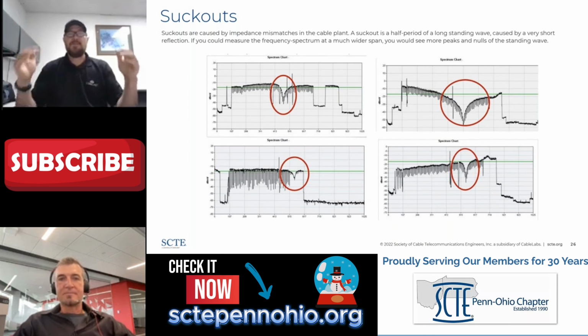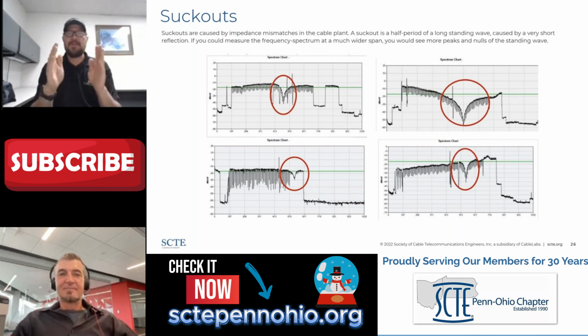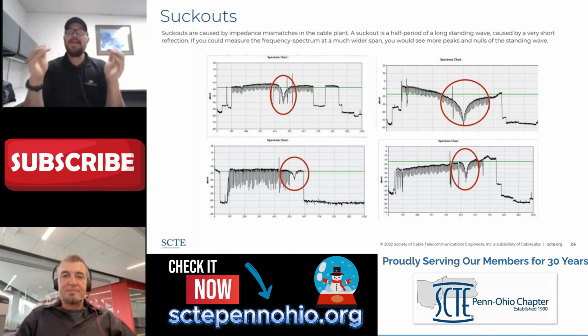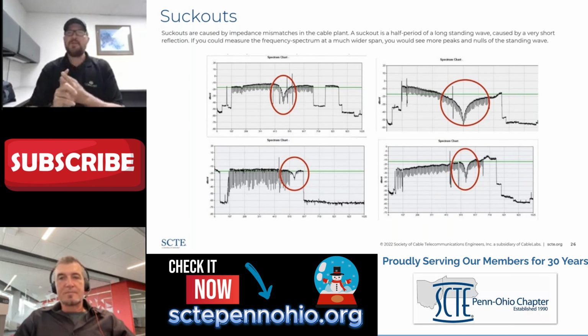Oftentimes when you see a suckout, you may also have a leak at 600-700 megahertz because of the geometry, the size of the component, and the fact that it's defective, meaning water corrosion or something impaired. So it's not uncommon to see high frequency leaks and suckouts associated with the same things. So when you're chasing a suckout, turn your sniffer on.